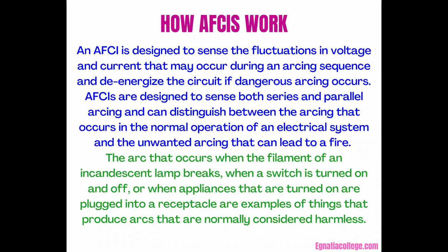How AFCIs work. An AFCI is designed to sense the fluctuations in voltage and current that may occur during an arcing sequence and de-energize the circuit if dangerous arcing occurs. AFCIs are designed to sense both series and parallel arcing and can distinguish between the arcing that occurs in the normal operation of an electrical system and the unwanted arcing that can lead to a fire.